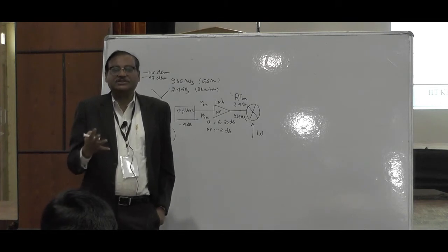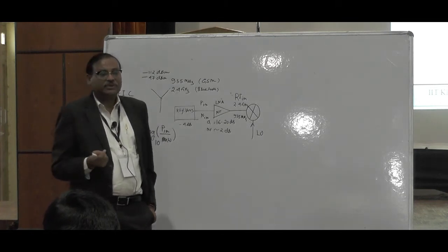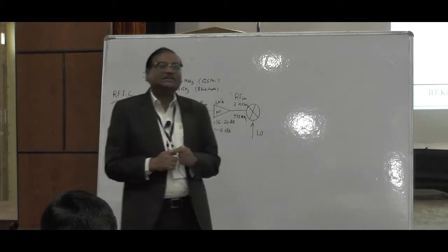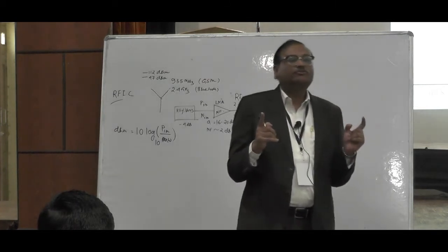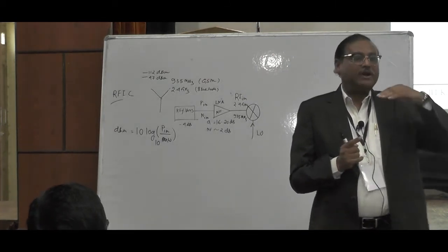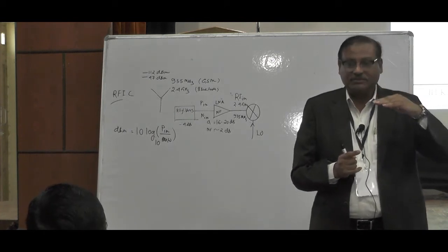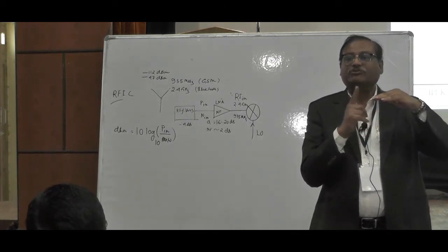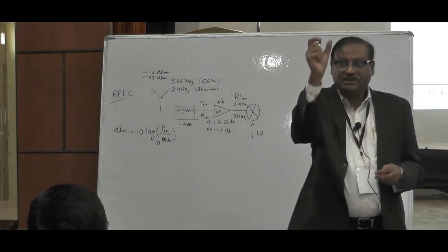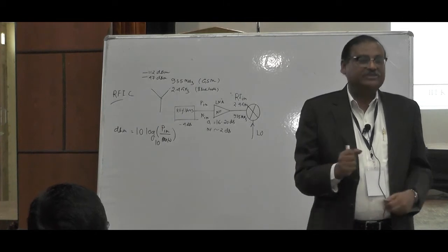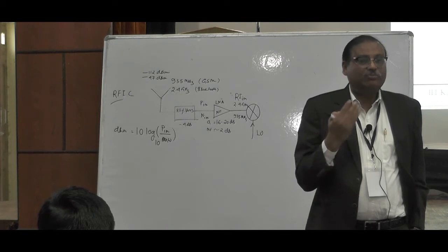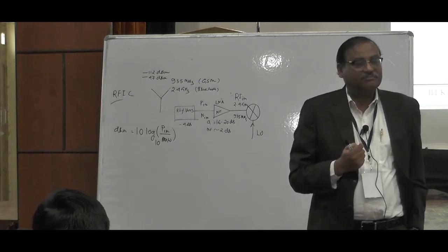Then through a frequency synthesizer, you are generating that local oscillator. For example, my voice signal is within the range of, say, 5 megahertz. So 2.4 gigahertz is my carrier signal. Then 2.405 gigahertz is the carrier plus this. So this is the range, 5 megahertz. This is the frequency range at which my voice signal is carried on a 2.4 gigahertz carrier channel.